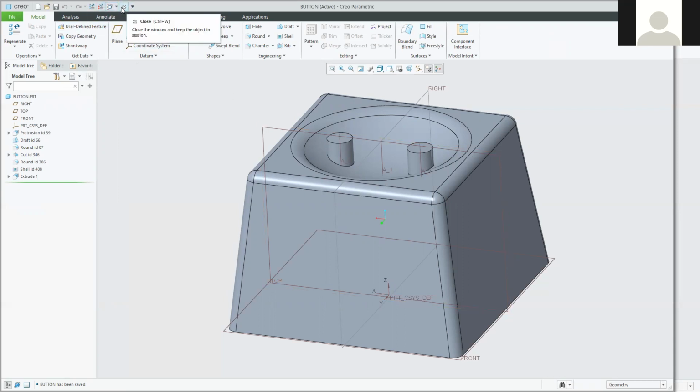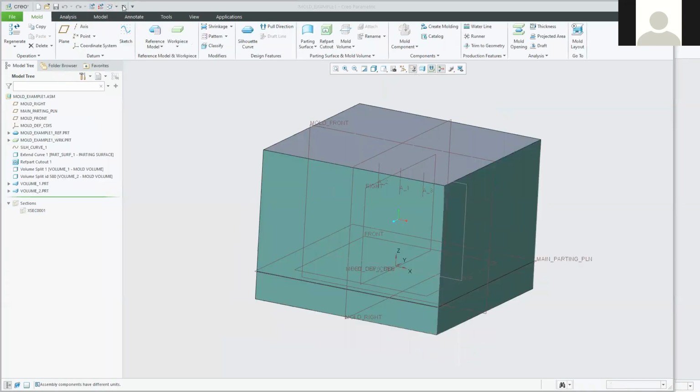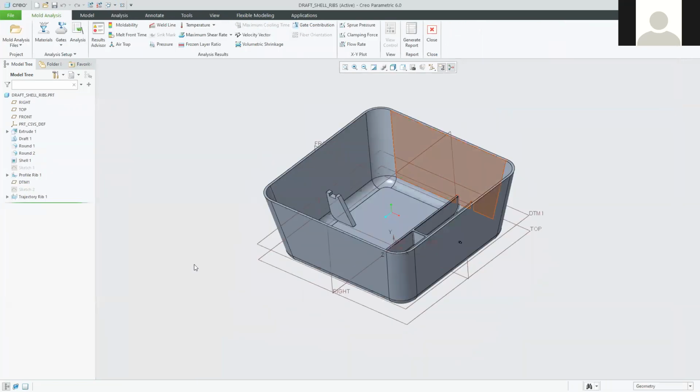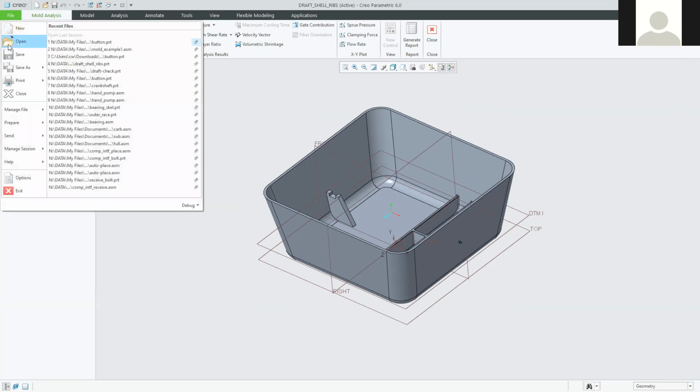So let me shut this part file down, and I'll shut that down as well. You can see when I just close things, I'm just clicking on that white X at the top. That shuts down whatever I have on the screen at that point. But all those items, that whole assembly and those part files that I had on the screen before, the system still has them held in RAM. So they're all still held in RAM. And if I intend to now load a copy of them from the hard disk, I have to flush those copies of them out of RAM first.